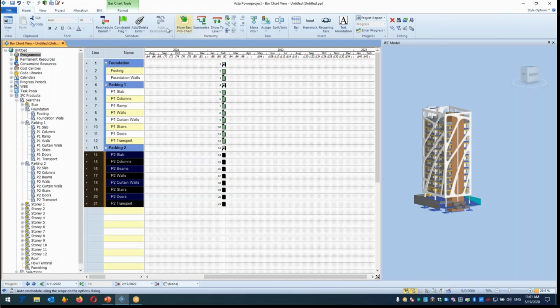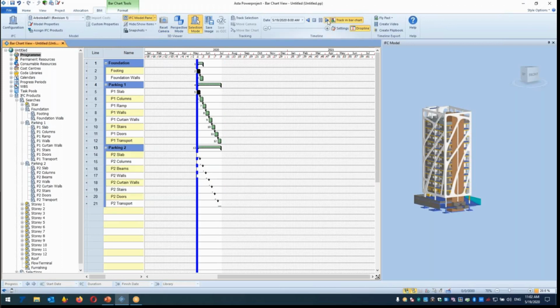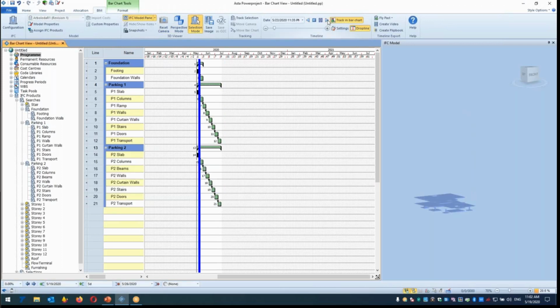And then when you schedule with F9, you can simulate it. Now, it's very fast. I mean, you can do it in a couple of hours, a very fast schedule, by selecting the auto task creation from the selected items, and you can have a simulation. It's not taking too much time to learn to create the schedule.